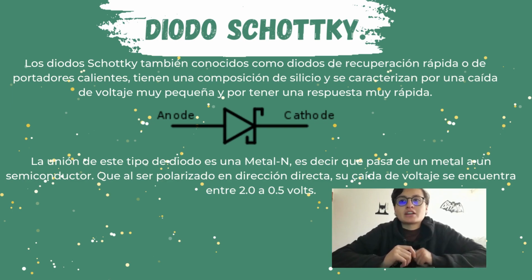Okay, in this opportunity, I will explain Schottky diodes. Schottky diodes, also known as fast recovery or hot carrier diodes, have a silicon composition and are characterized by a very small voltage drop and very fast response. The junction of this type of diode is metal-N, that is, it goes from a metal to a semiconductor that is polarized in the forward direction. Its voltage drop is between 0.2 to 0.5 volts.